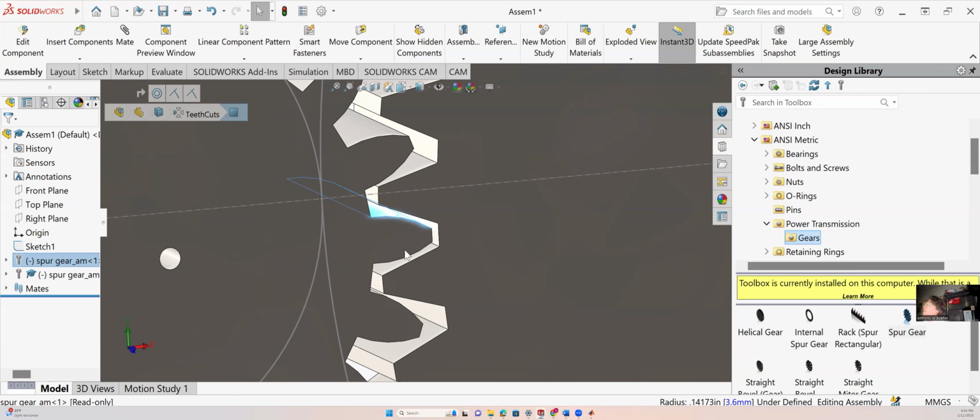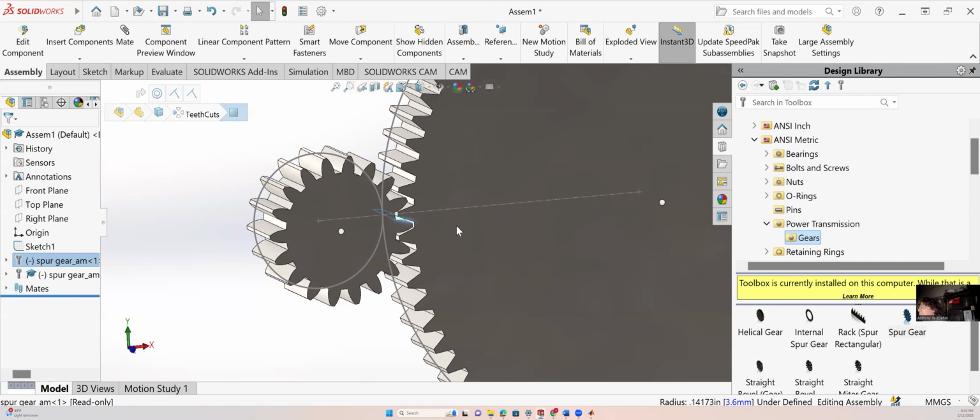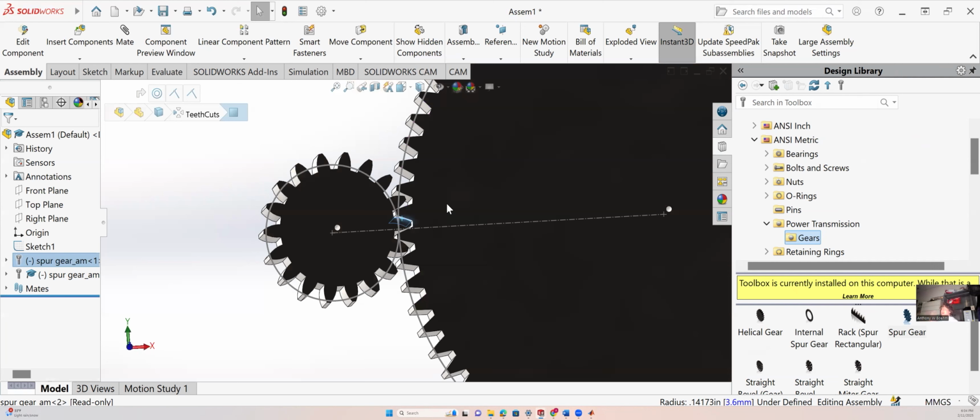All right. And if you don't have a consistent pressure angle like that, then you're going to have undulating forces. Okay. So if you have basically two square pegs that are interfacing as a gear, then that pressure angle is going to be changing quite drastically. So yeah, the reason why you have a curve on one and not the other is so that as they're rotating, the pressure angle remains consistent, and therefore your torque transmission remains consistent. Okay, cool. So we have our gears.